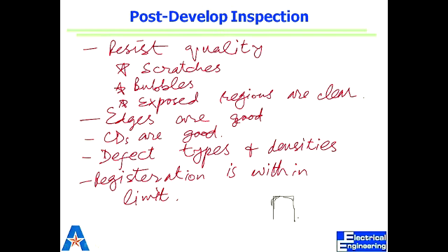So that brings the notion of the size on the mask and what we register. We are going into registration because that's something we do in alignment. When we are doing alignment, we generally saw what alignment is. So alignment is bringing them together, right? But once you push the pattern and exposure happens and we develop, then we have to see what we have got registered on the resist, which may be different because of the play in the machine. What gets registered on the resist is your critical dimension. But it's not necessarily the dimension of the device. It does not have to be. It may be at a different level.